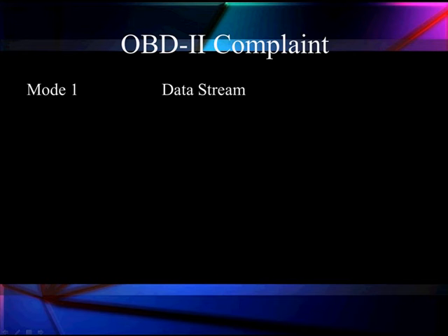I want to give just a couple minutes to talk about the OBD compliant features of the Power Stroke. Now, we have mode 1, the data stream. We're going to show you in this program how we specifically focus on areas we want to test for specific functions and how to group data together for it. One of the strengths of this program is we're going to rely heavily on data stream to point us in the right direction. There's a number of ways to get direction.